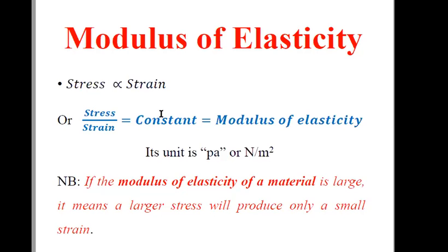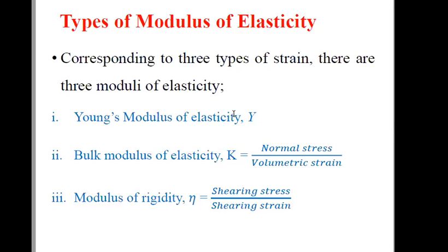So this is your Young modulus of elasticity, which is represented by Y. Bulk modulus is represented by B or K. I would request you to use B, because K is also used as compressibility, and B is equal to 1 by K. In many problems K will be used as compressibility and bulk modulus is 1 by K, so it's advised to use B for bulk modulus.